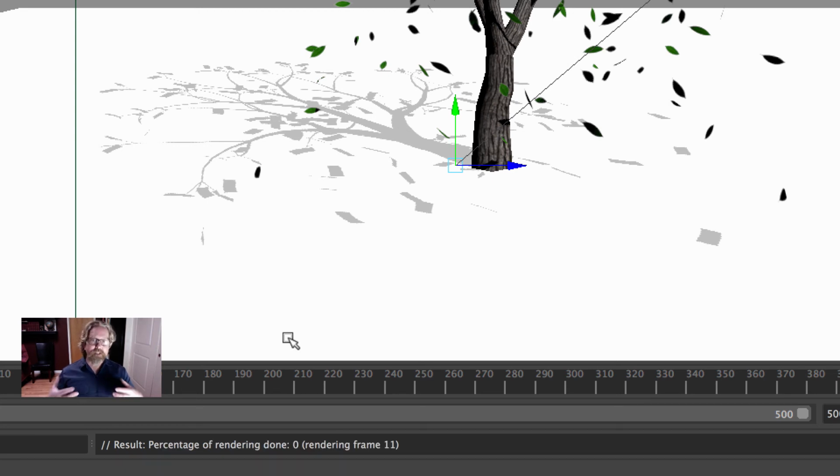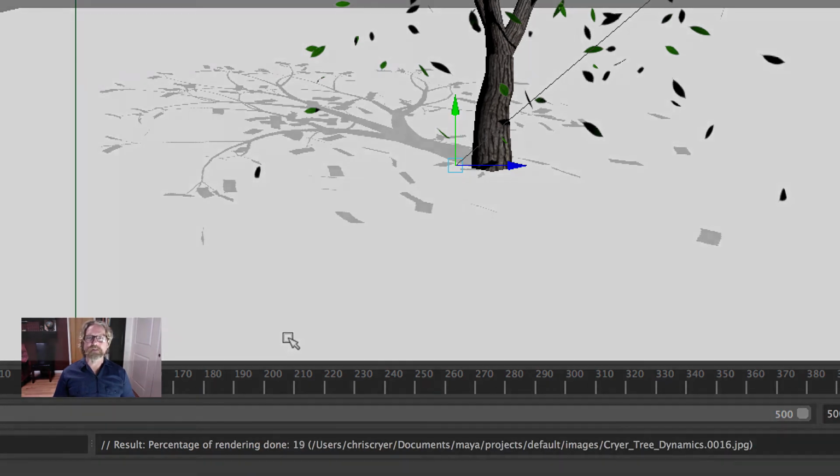Now, if your renderer didn't get going, what we'll have to do is come back and bring down the quality or bring down the size. So bringing it to intermediate, maybe you're doing a 600 by 600 rather than a 1K, and you have to bring down the size, bring down the quality. But 1K with this simple scene, even an average computer ought to be able to render this. Okay, we'll pick up when this finishes in a few minutes.